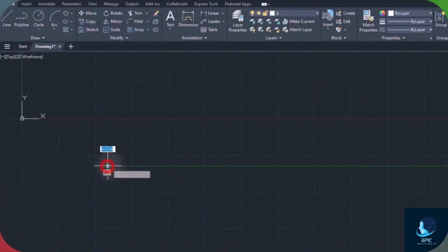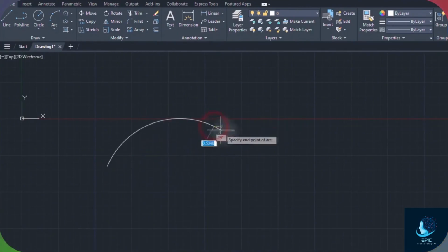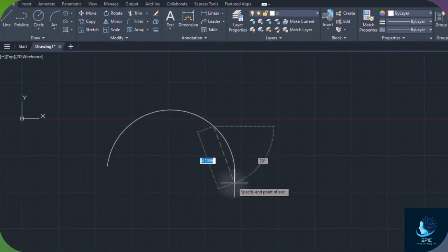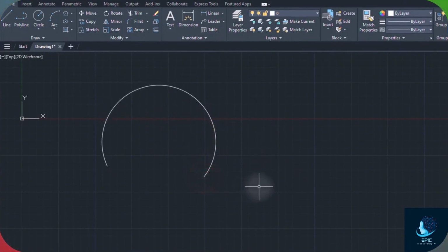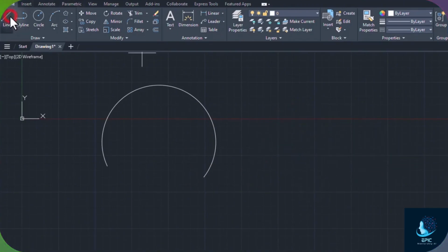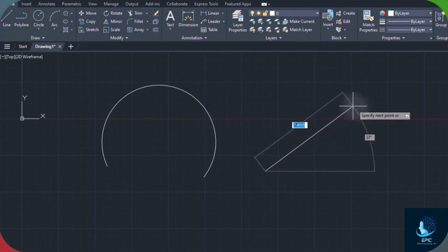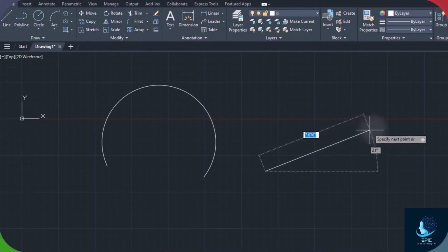AutoCAD offers several measurements and drawing aids to make your drawing effective and efficient. While drawing, AutoCAD provides a live preview of the object in progress along with its measurements. To undo the drawing, simply press the Escape key. When drawing a line, AutoCAD shows the angle degrees with respect to the x-axis and the length measurement in accordance with the unit set for the project.